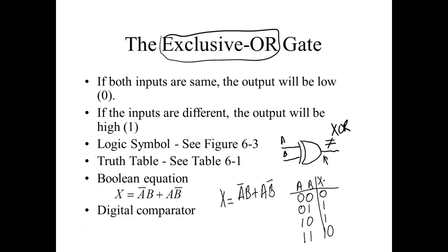I think we're going to use a 7486, or a version of it. And hopefully by now, I think we've talked about it before, 74 is for commercial grade TTL. And then we came out and we had what we call the standard series. So when we talk about TTL compatible, we're talking about being compatible with the standard series. So we're going to use the 7486, which is an exclusive OR gate. But you might see a